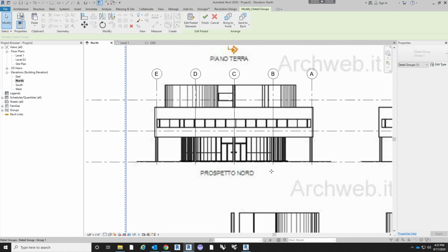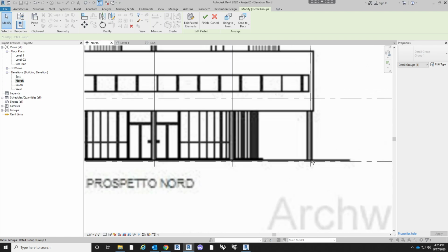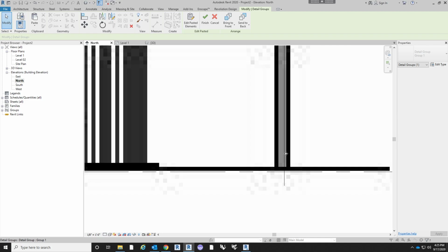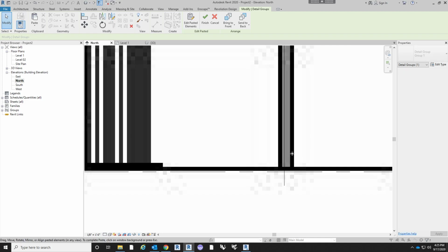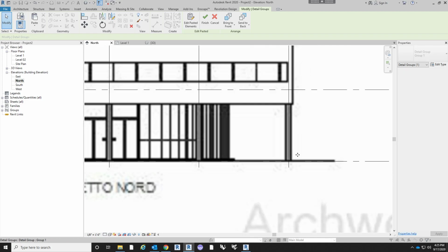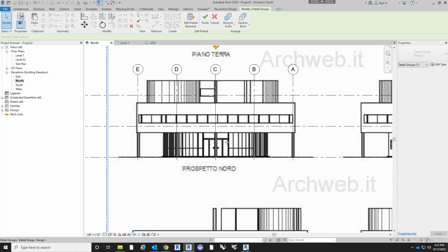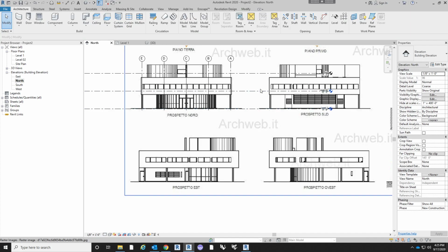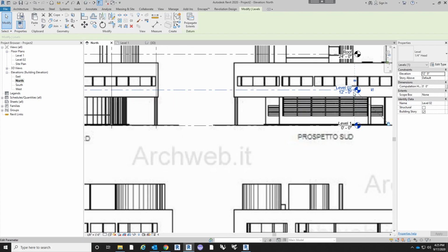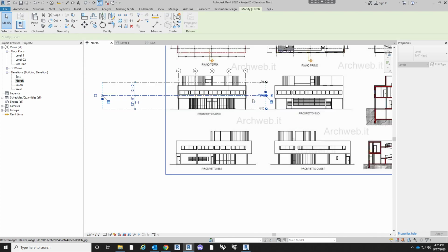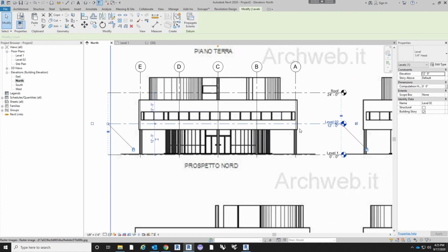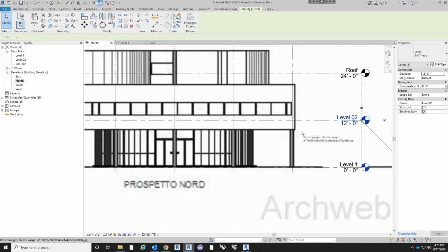And one thing about Revit, really random, but if you zoom in and use the arrow keys, the movements of the object will get incrementally smaller. It looks like it's trying to keep up with the pixels, so we'll just center it there. All right, and then let's adjust the levels. First, let's adjust them in so that they are only extending through the immediate building, and then let's adjust the height.